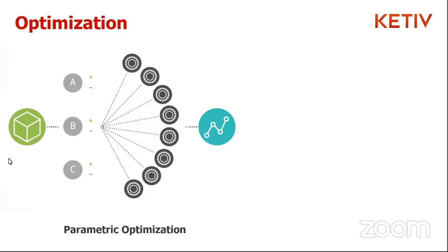You have to first select your baseline geometry, your foundation, and then choose the geometric parameters to be changed, right? What you will need to do then is specify an acceptable range for each of these parameters, and then run these analyses, hopefully in parallel, so you get your best combination of results, and you're able to play around with them and visualize the results at every single one of these ranges. Now, this again focuses almost exclusively on the geometry itself.